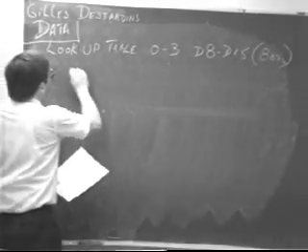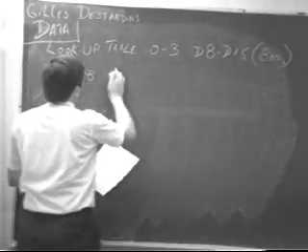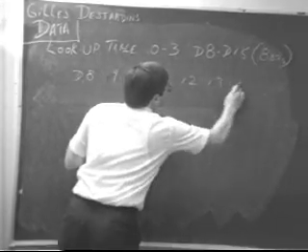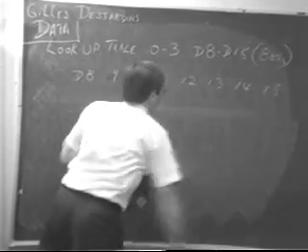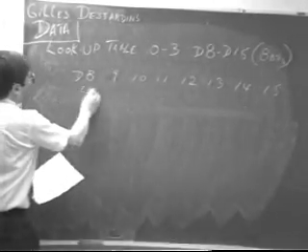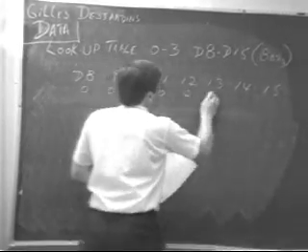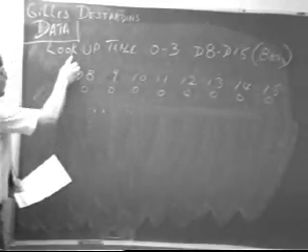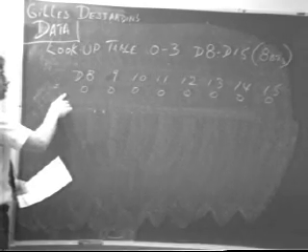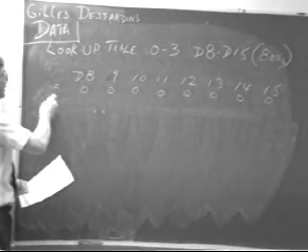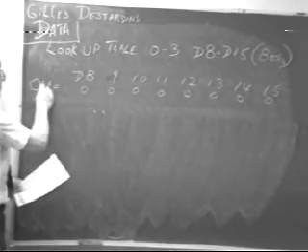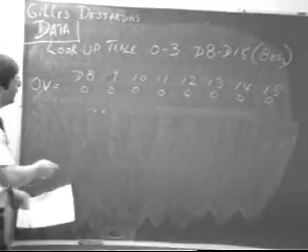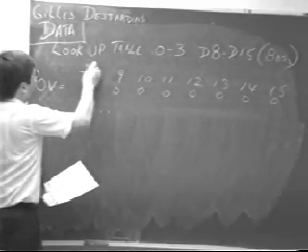D8 to D15. When they're all 0, this is the lookup tables, and the data is equivalent to 0 volts, D8 being your MSB.